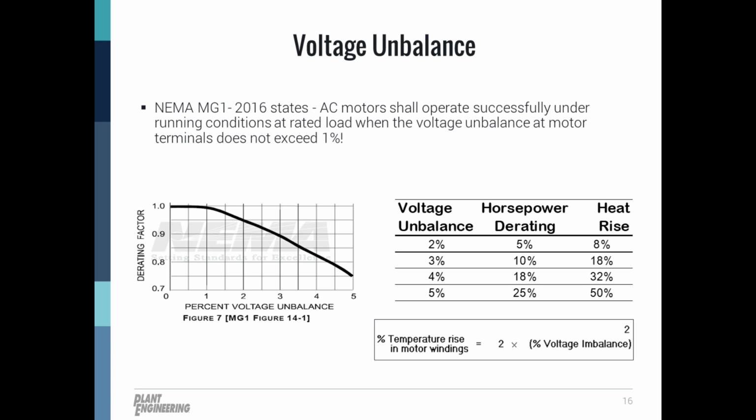So of course, the voltage unbalance isn't the only cause of current unbalance. Unbalanced winding resistance can also lead to current unbalance. If you're measuring a current unbalance in the field with an amp meter, with your motor loaded or unloaded, then it's always a good idea to de-energize the motor and measure each phase-to-phase winding resistance to verify the baseline unbalance.